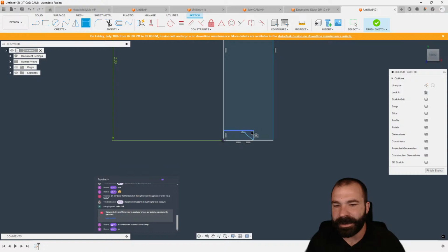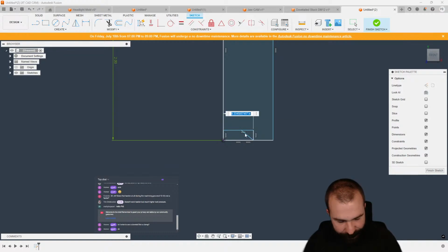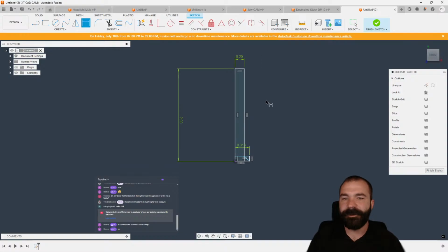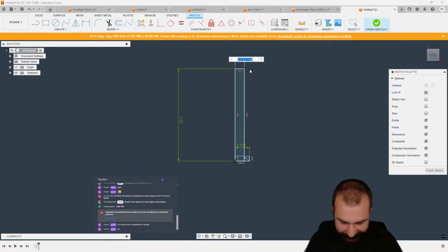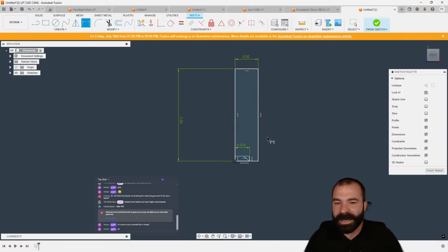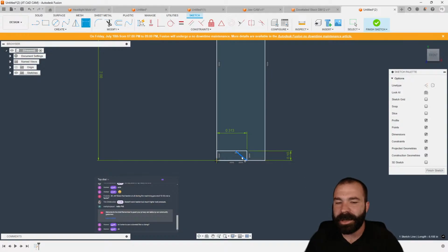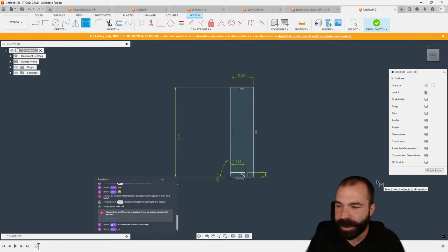And then we would have something like our dovetail width. Now this number, again, I don't know what it is off the top of my head. Let's just say it's 0.625 divided by 2. And then lastly, we can give this, let's say it's going to be 1 inch total width divided by 5. No, that's not what we wanted. 1 divided by 2. As you all are seeing here, I'm able to configure and set this up based on those dimensions, right? So the biggest difference between a normal sketch parameter and a configuration is the configuration allows you to hot swap dimensions, right?